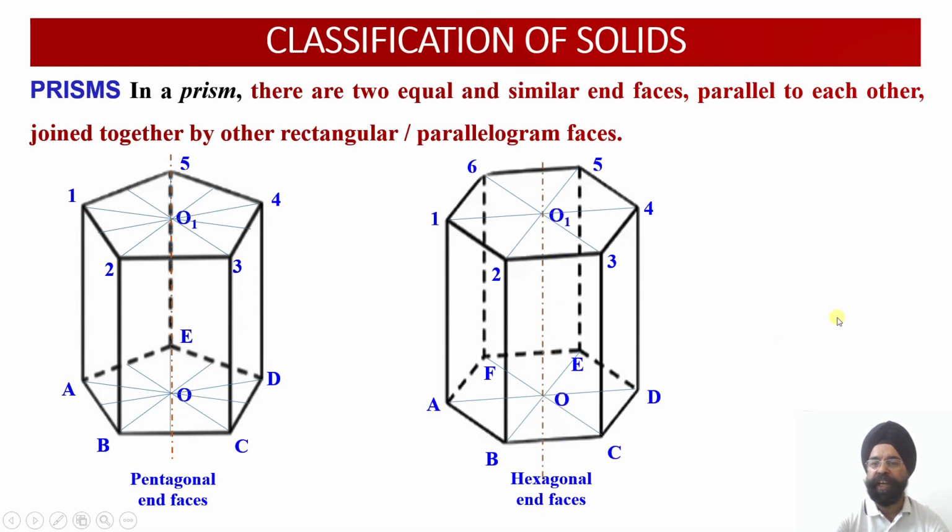So the number of points which I have to deal with in every view will be 2n plus 2. So 6 plus 6, 12, and 2, 14 points I am required to draw. So in order to draw the projections of an oblique solid, that is an oblique hexagonal prism, 84 points will be required to complete the given problem.